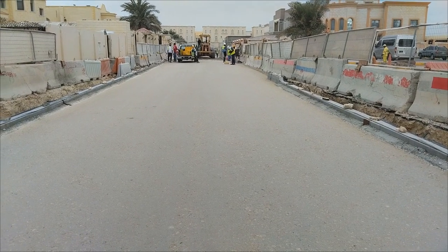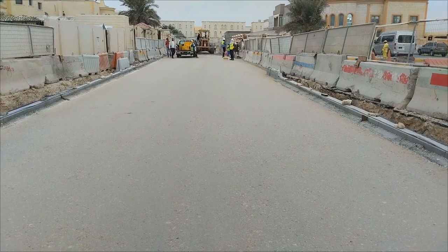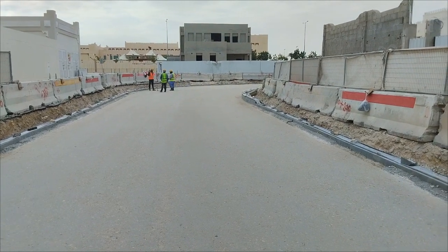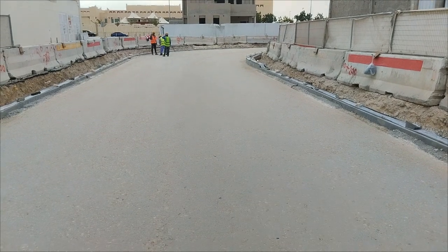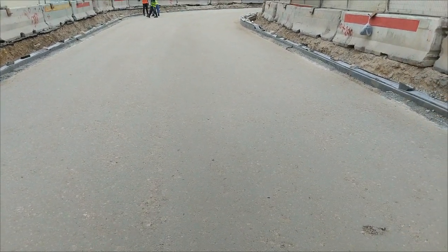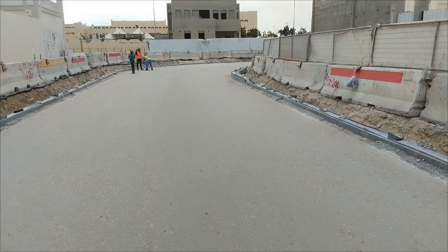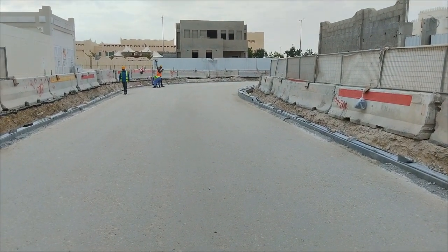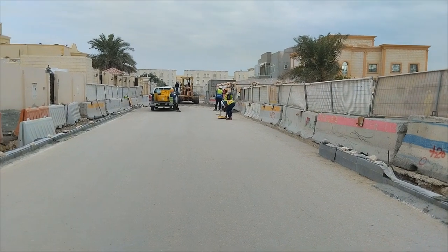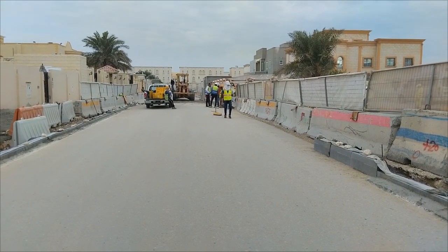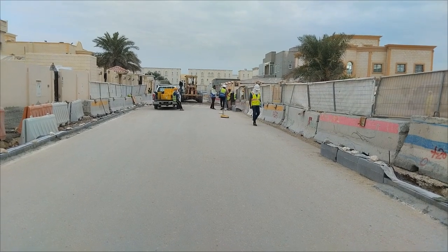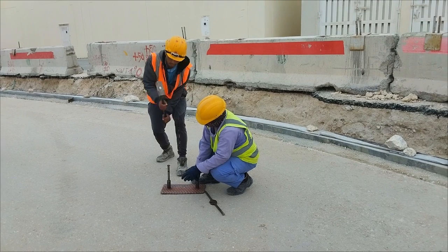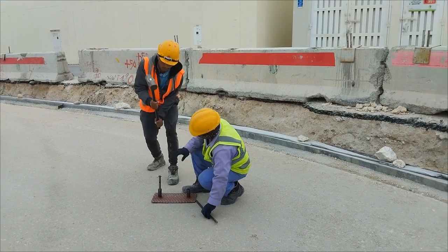Our team verified everything, the surface inspection, and now we'll be conducting tests on top of the road base. We are conducting 3 tests. First, the nuclear density gauge test will be conducted every 200 square meter area. 1 test will be conducted in a 2 meter radius. In the 2 meter radius, 3 points will be taken, and the average should be taken of that, and it should not be less than 100% compaction.